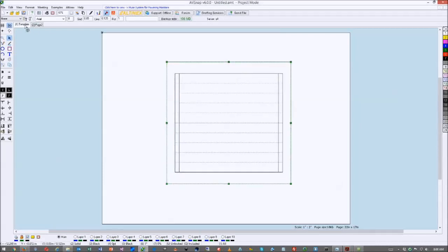All right. And to make it a template, I have to click on the key right here on the left-hand corner, the set as a template, and make it a hidden page. So when I print, I don't have to see this page. So I'm going to also move this tab to the right. So by clicking on the middle of the tab and just dragging it, you see there's a little red vertical line. You can drag it behind page 2. And at page 2, I will call it rack elevation.